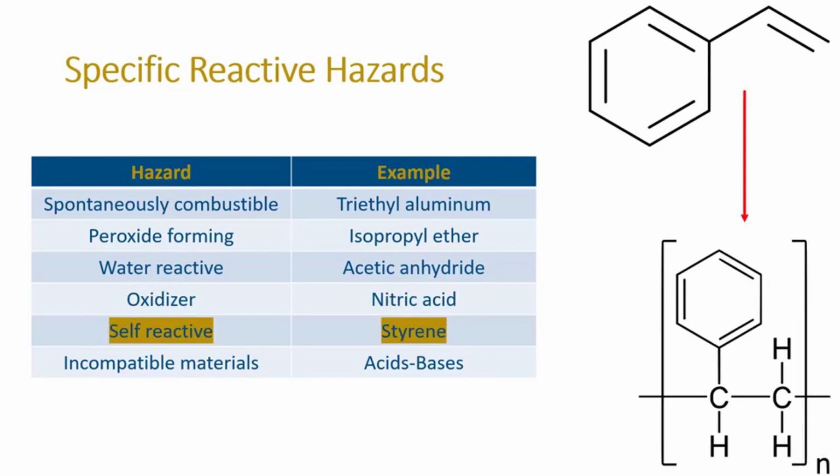Self-reactive materials also present a reactive hazard. This is because the reaction often accelerates with dangerous consequences. On safety data sheets, self-reactive materials are often identified as being self-reactive. And on the National Fire Protection Association diamond, these materials should receive a reactivity rating of 1 or higher.